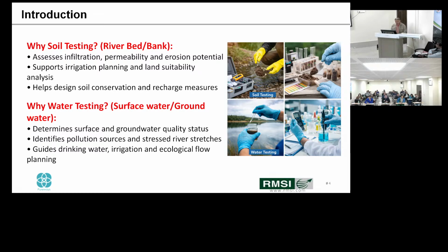So first, why do we need to do soil testing of the river beds and banks? To assess the infiltration and the permeability of the soil, and also it supports the irrigation planning and the land suitability analysis, which means to test the soil for different types of crops to be planted over the command area.